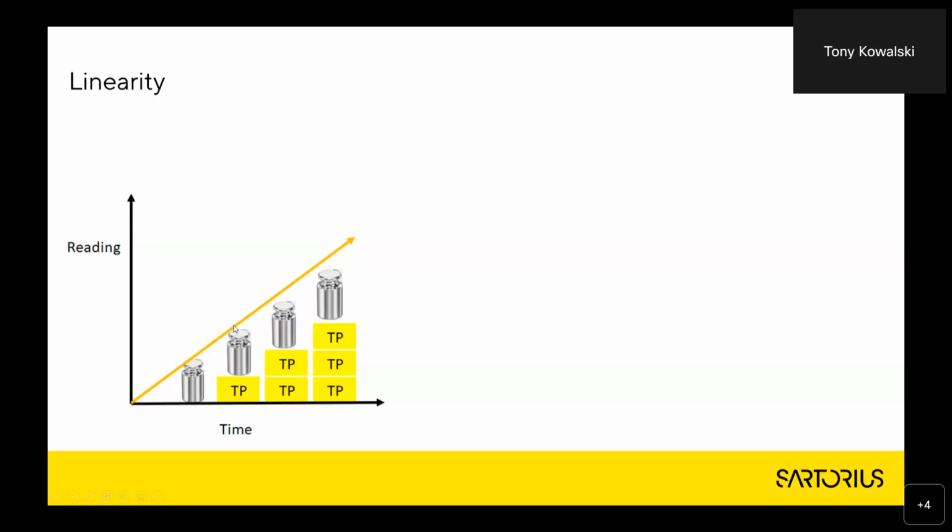We take it off, we add another test weight on, tare it back to 0, so it's a tare weight, and then we put the same weight back on again, and we measure its value at this part of the range. And finally, we tare off enough mass so that we can test it at the nominal.